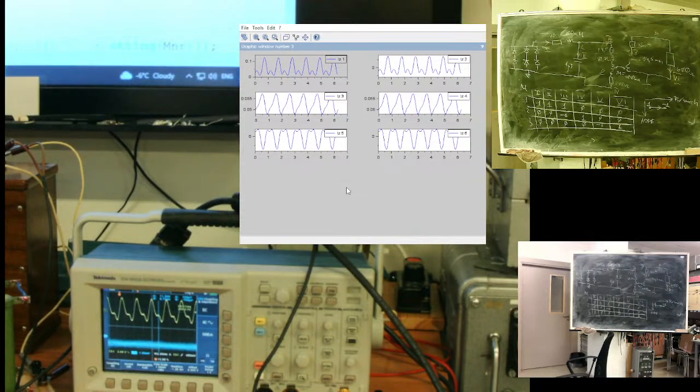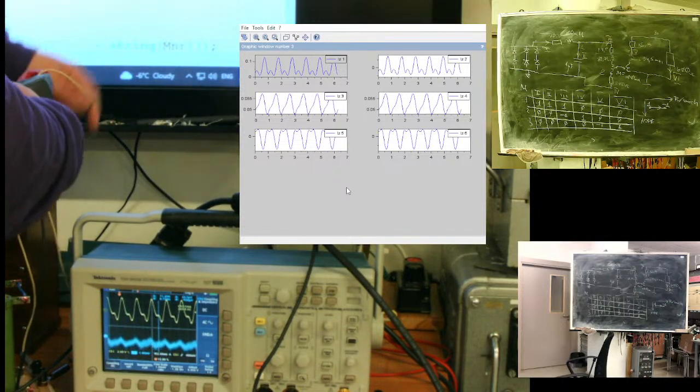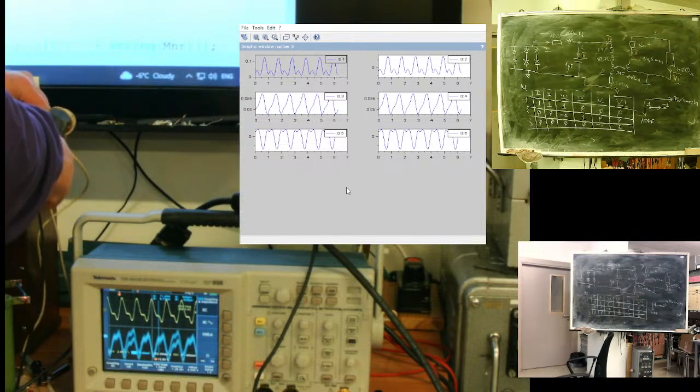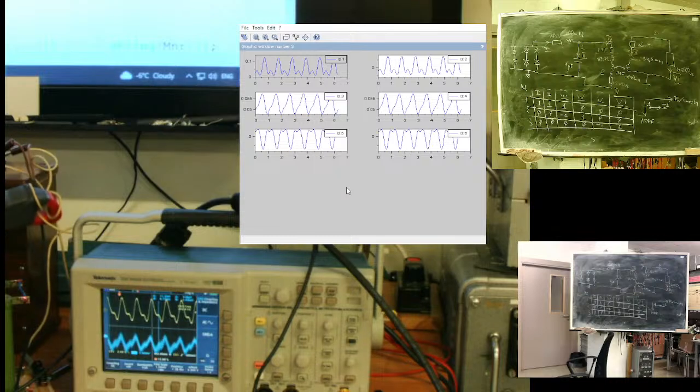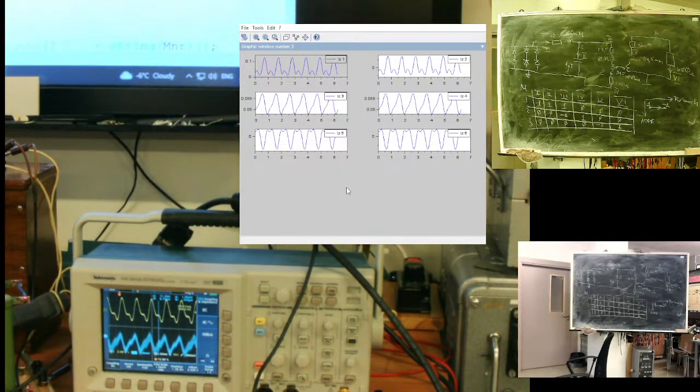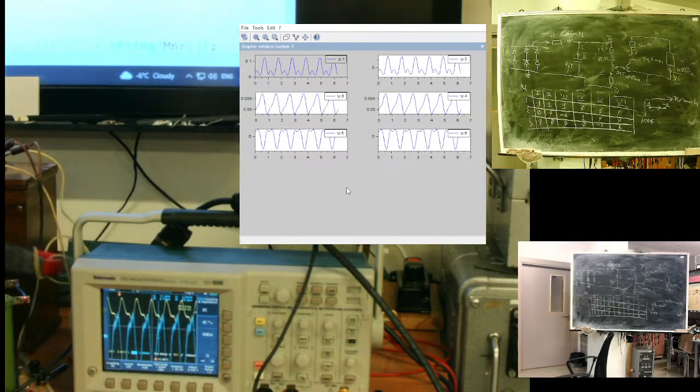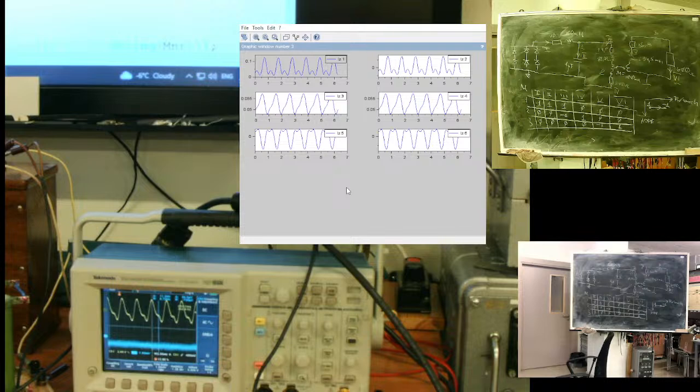It's above sensitivity of this clamp because it's designed for 20 amps. It's on branch 5, but it's quite disturbed. Voltage similar, but okay, it's a reactive load. We know what the voltage is. I need a different one. This clamp is too big.